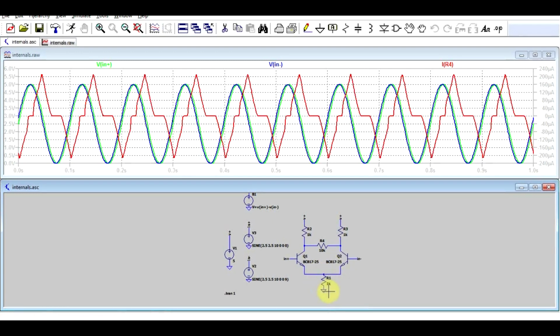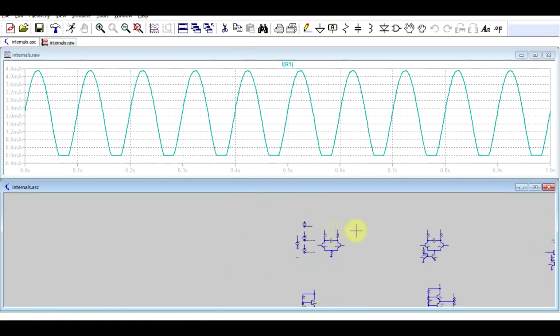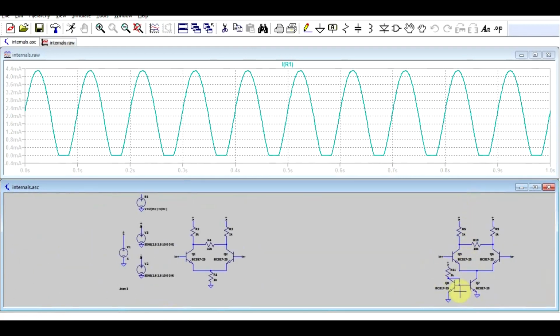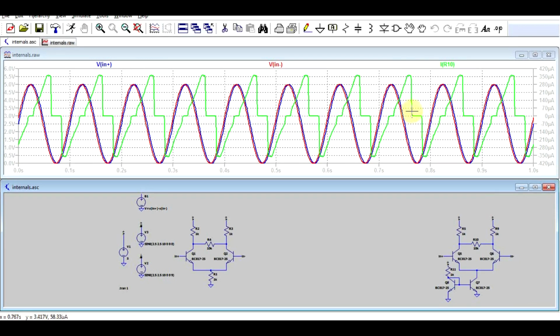This lower resistor. Because it's a resistor, the current going through the comparator stage varies. So it's a nice sine wave. This is completely unacceptable if you want a proper OpAmp input stage. And normally this is replaced with a proper current sink so that your comparator operation is a bit more stable. So we'll be analyzing this circuit in which the resistor has been replaced with a current sink to better understand what is going on. So here again we have the same behavior. We've got the output current of the comparator flattening out when the two voltages are low.